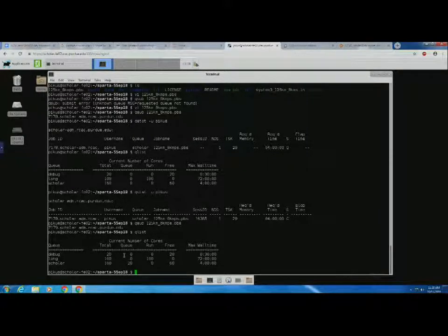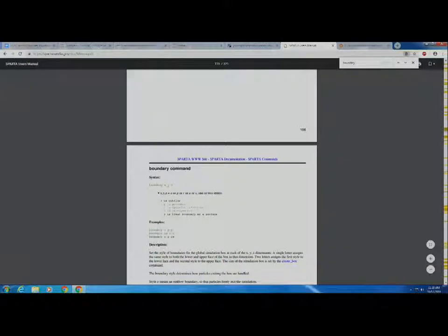I should say, there's a possibility of an axisymmetric simulation, which is a rotational one, so it's like a 2D problem, but it's a simulated large cylinder instead of a large box. In that case, my first recommendation would be that before you get to axisymmetric, you want to start with just a 2D case with a symmetrical boundary instead of axisymmetric. Make sure that looks okay. There are reasons to do axisymmetric, but just in the way SPARTA works, you have to play around with a few other commands. I'll try to run through those and show them quickly.